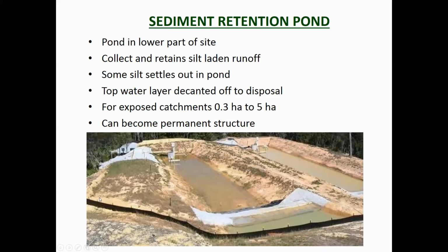So the water flows in there, so you can see that there's the dirty water diversion drain there, I think it is, and then it's flowing into this bit here, which is the forebay. The forebay is designed for easy access, so you can drive an excavator up here, you could drive trucks up, and the forebay is picking up most of the sediment. Most of the heavy sediment will get into the forebay and drop out there. So it's the first level of treatment, and then it flows over this bund here.